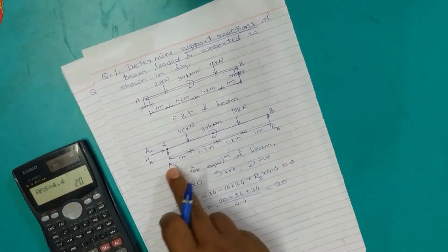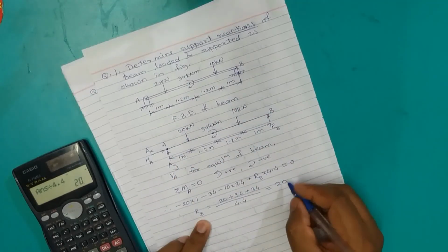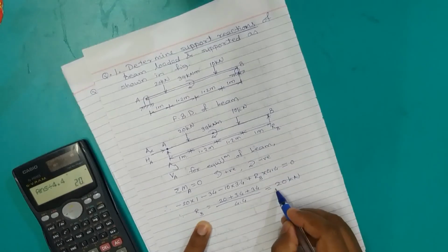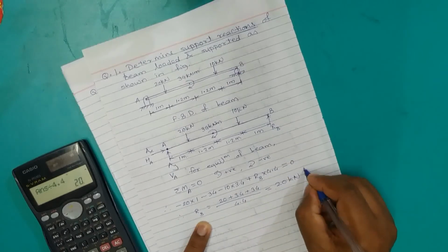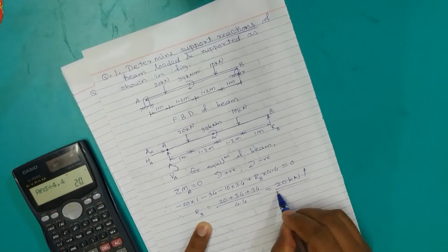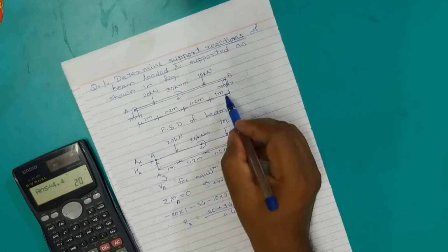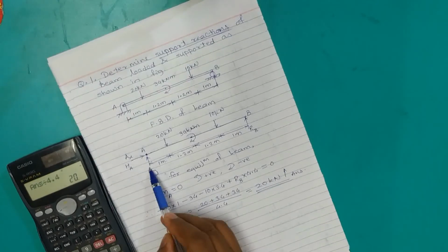All the loads are given to us in kilonewton. So this reaction RB, whatever we have calculated, also has to be in kilonewton only. We have got a positive answer for the assumed direction of RB, so our assumption for the direction, upward, is correct. This is the roller reaction RB, one of the answers. Still we have to find out AX and AY, remember.